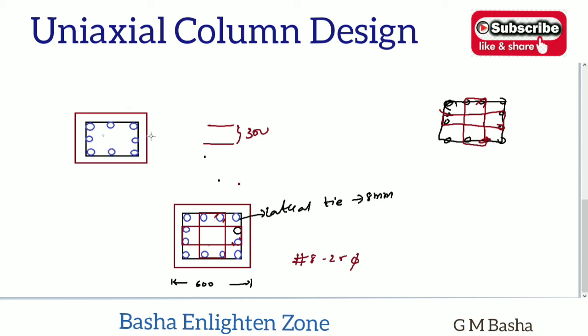First, covering all the outer bars, the 4 bars, and for the internal bars you have to give like this, taken from the starting here to the ending here. Like that you also have to provide for 8 bars of 32 dia. So this is the cross section. For the previous problem I also showed that cross section and elevation. For this one I am stopping here because the entire procedure will be the same.